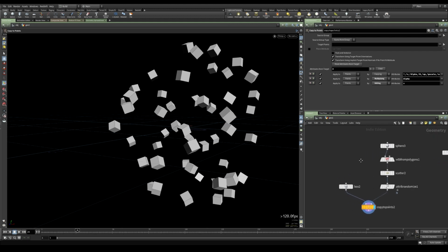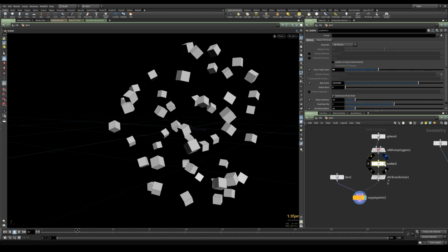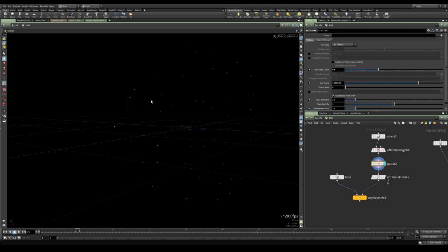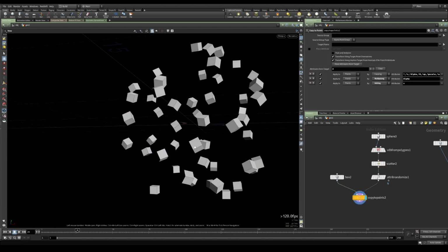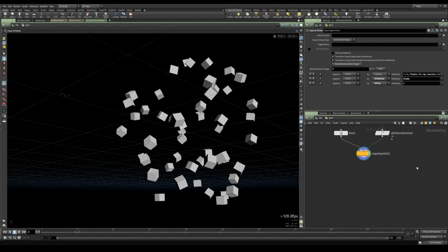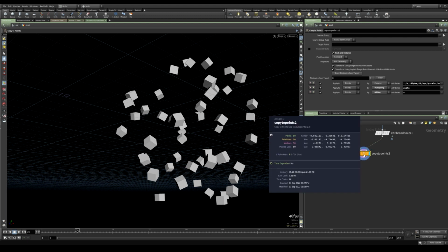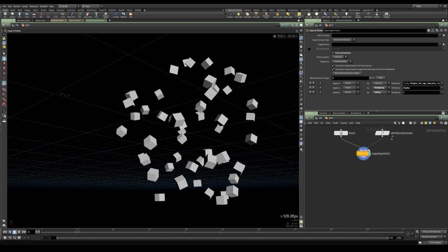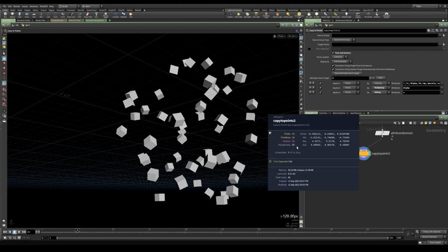So for the sake of this explanation, let's say I don't have these points, which are the ones that I'm going to get at the end, and I just have this as regular geometry. I can think of two ways to generate those points, and both ways are intended to work with packed geometry, which is basically the way Houdini creates instances of geometry. If you have a copy to points, you can create packed geo just by enabling this pack and instance, and Houdini will create a packed geo for each point you scatter the geometry on. So we have 50 polygons for 50 boxes and 50 points.